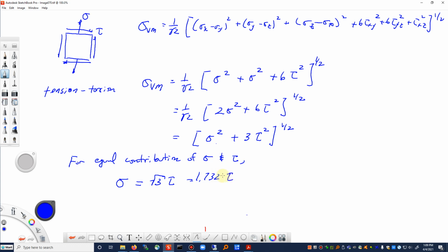Okay, so what that's saying is the shearing stress is in a way more damaging than the sigma, damaging in the sense of contribution to plasticity or the equivalent stress. So the von Mises stress is used usually as a yield criterion that determines plastic flow, but it goes beyond that, and we'll talk a little bit about multiaxial plasticity here in just a moment as well. So if I were to show on a phase plot, let me make a new slide here. On a phase plot, first I'll draw my stress state.